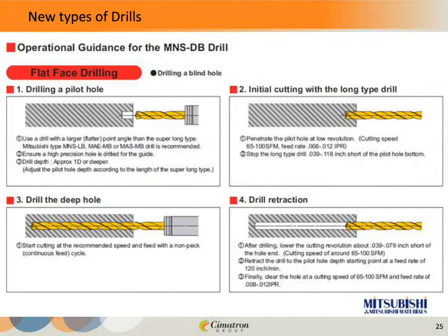Okay, next we're going to look at the different operations. So for coming in on a flat face, again speaking in generalities, if the diameter to length ratio is less than 5, maybe we don't need a center drill or a pilot.